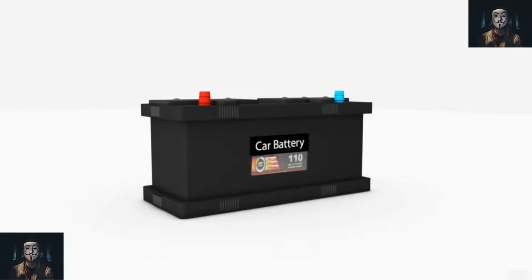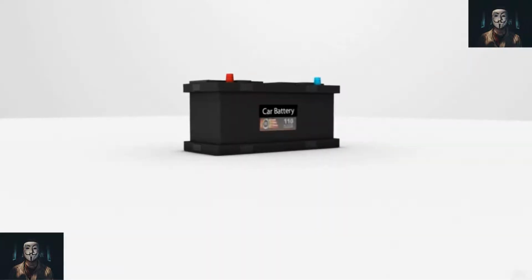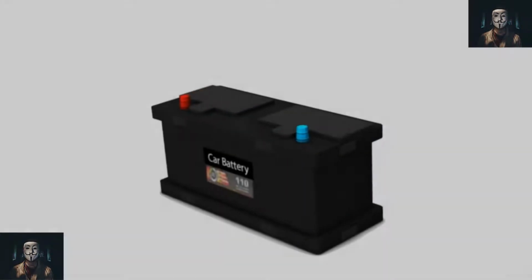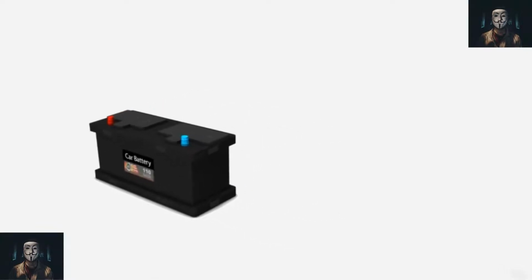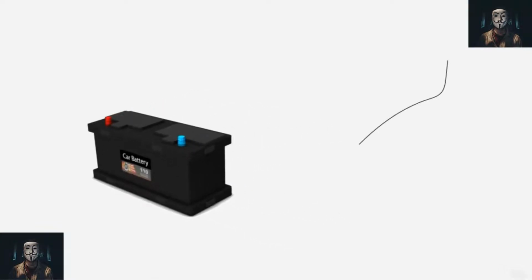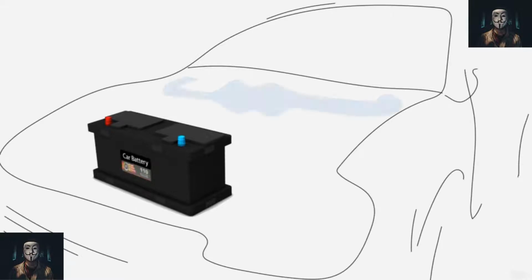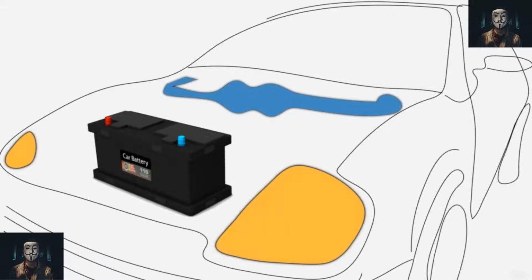Near the fully charged state, some hydrogen and oxygen may be lost as gas from the battery vent. Some water can also be lost by vaporization in hot weather. With older batteries, this meant that battery electrolyte needed a regular inspection and topping up. Only water is lost from the battery, and therefore only water should be used for topping up. Any contaminants will affect the chemical reaction in the battery and therefore the performance.